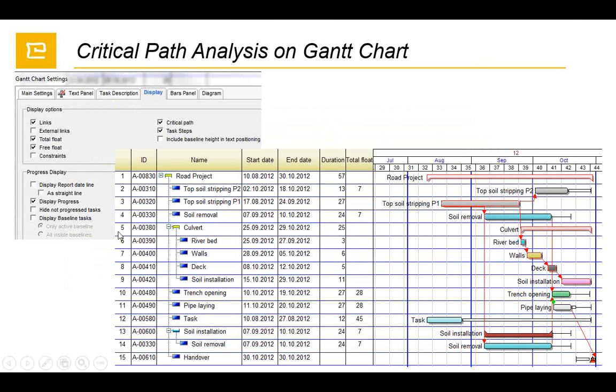Tilos also provides a Gantt chart, and if you are interested in some cases, for example procurement works and other works, you may want to use the Gantt chart. It is integrated with time distance, so whatever you create here, if you give the distance values, it is already created there. We can monitor the critical path here as well, but if you are using Primavera or Microsoft Project or other systems for critical path analysis, you can continue with that. In Tilos you can use it for the linear parts.